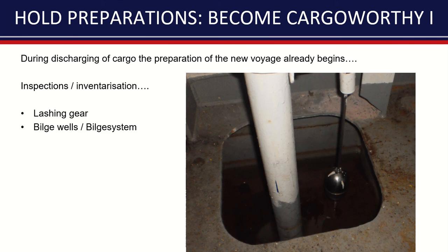The bilge well needs to be checked, and if we have grain or bulk cargo, there needs to be a covering plate so that the bilge well doesn't fill up with the cargo. Very important.